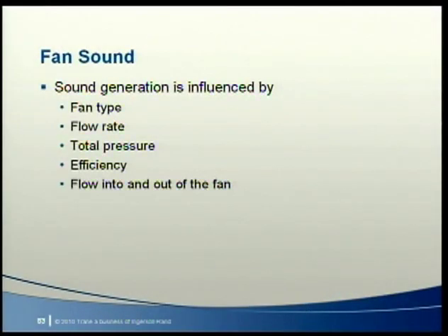The sound created by a fan is based on the type of fan, flow rate through the fan, total pressure, and the fan efficiency. That's just for the fan alone. When a fan is placed in a unit, drive system components and flow disturbances at the inlet and outlet change the sound produced by the fan. Once the sound leaves the fan, it is further impacted by other components of the unit. If the fan discharges directly into a duct system, the duct can also change the sound produced by the fan.